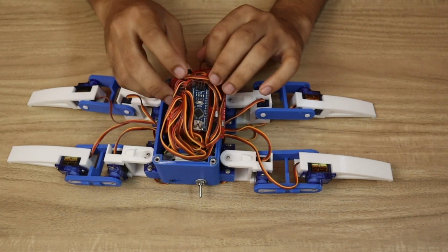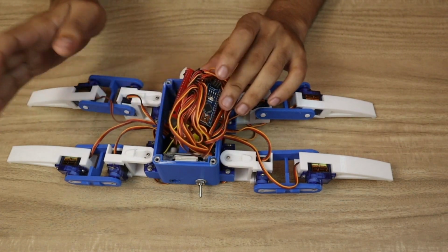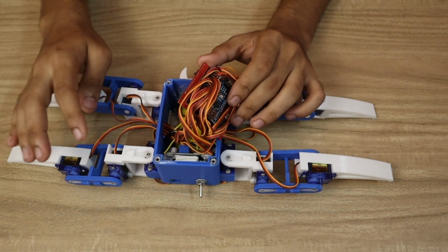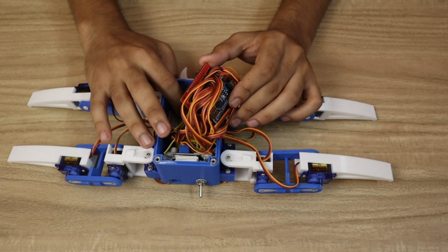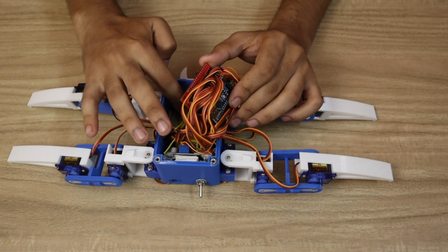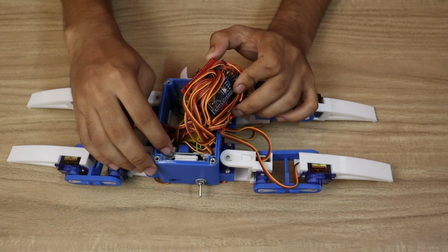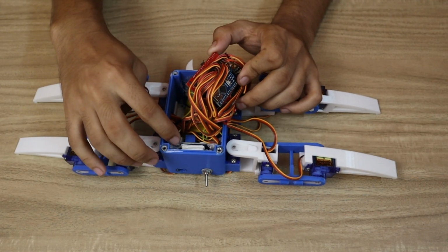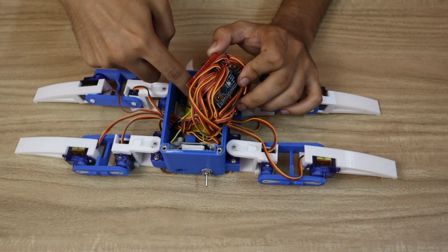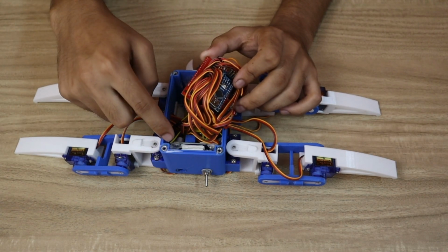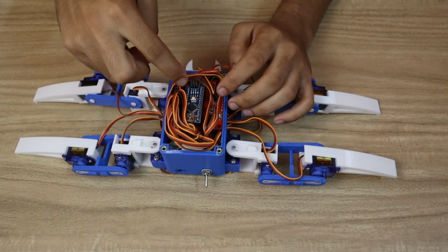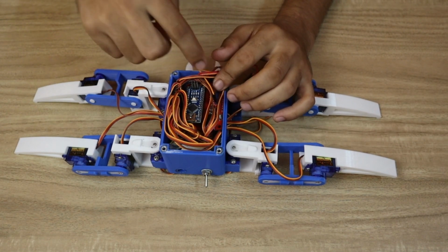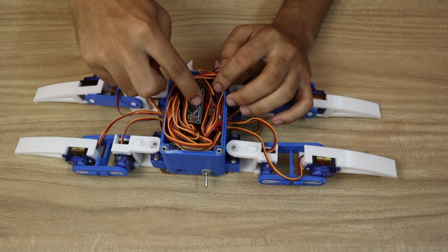Now, if you watched the previous video, you know how everything is connected. Still, I will just recap everything. Here we have two lithium-ion batteries, so we are getting around 7 to 8 volts. After that, we have the LM2596, which is a buck converter, which is converting this 7 to 8 volts to 5 volts. Now we are taking that 5 volts and giving it to this Arduino Nano shield, and from that shield the Arduino Nano is getting power.